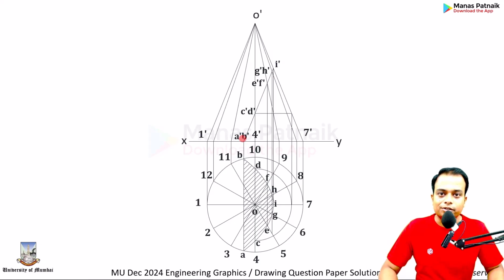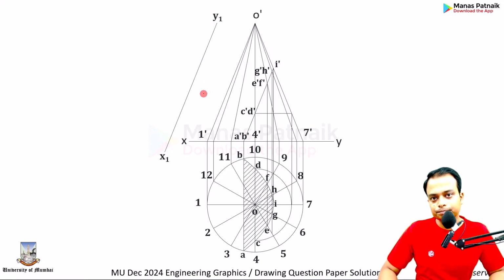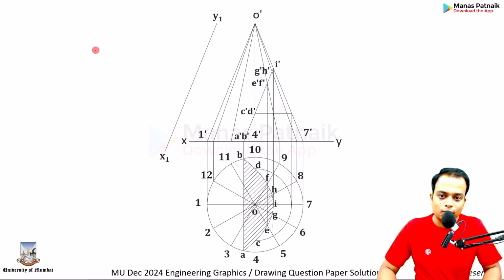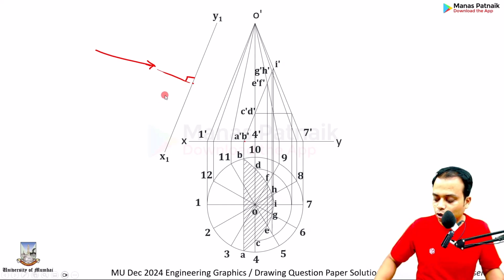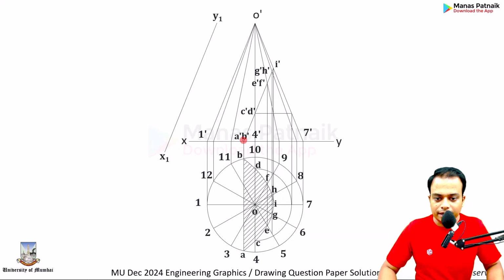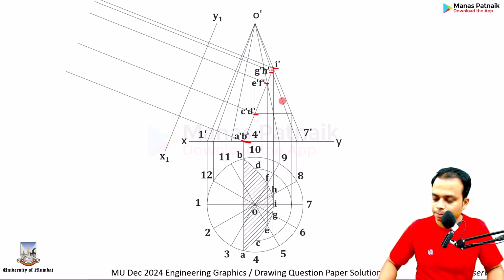Parallel to this section plane, draw an auxiliary plane. And now we wish to see from over here. So you need to, in this fashion, draw absolutely perpendicular lines. That means orthogonally. Draw lines through all of these points this way. You can do this. That's 90 degrees. Please note that. Now let's say you wish to have all of these points A, B, C, D, E, F, and this is for G, H, and this final line is for I, one single point.